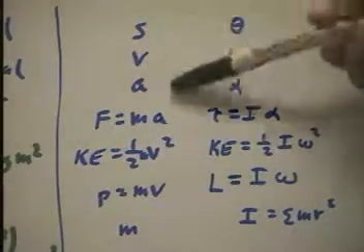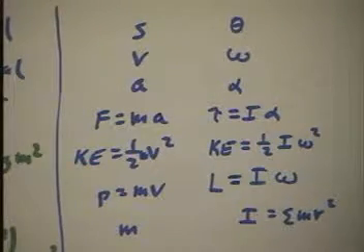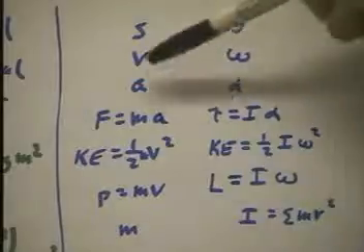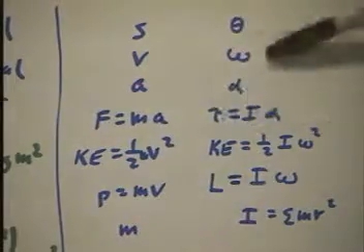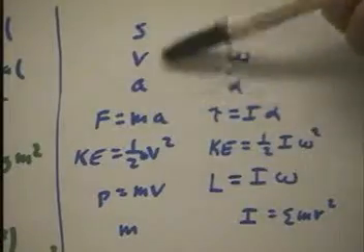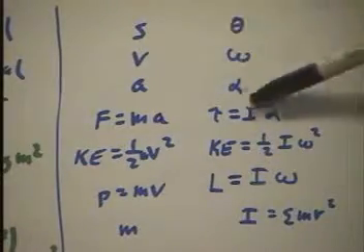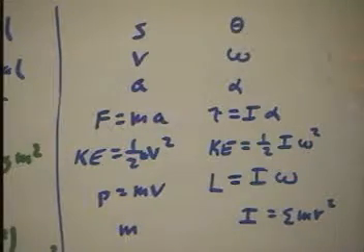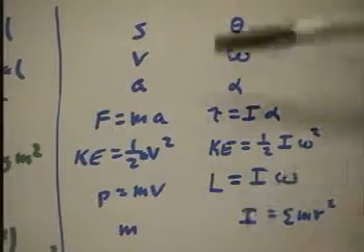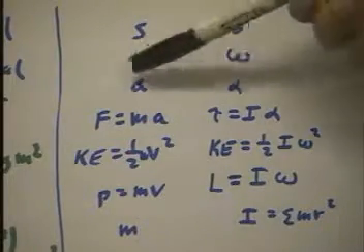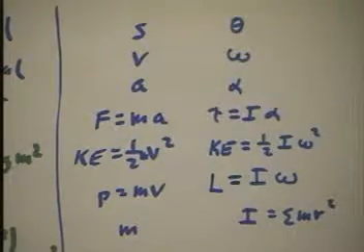And we can take the equations of kinematics in terms of time intervals, initial and final velocities, displacements and accelerations, and translate them directly. The reasoning that we use for these quantities is identical to the reasoning that we would use for these quantities. And I hope we have seen that in this course, so that we can simply substitute thetas for s's, omegas for v's, and alphas for a's in the equations of kinematics, of uniformly accelerated motion.